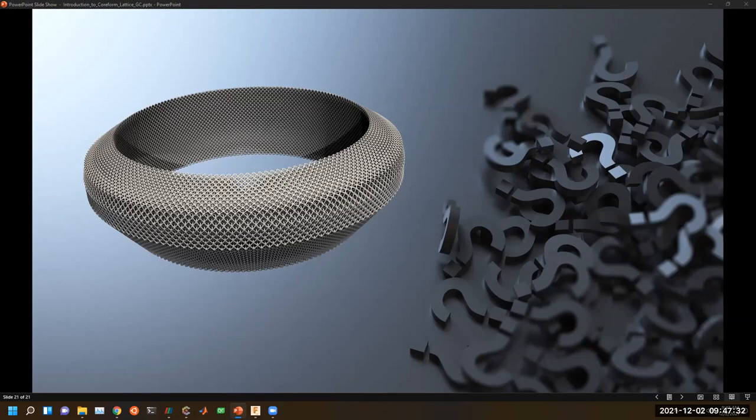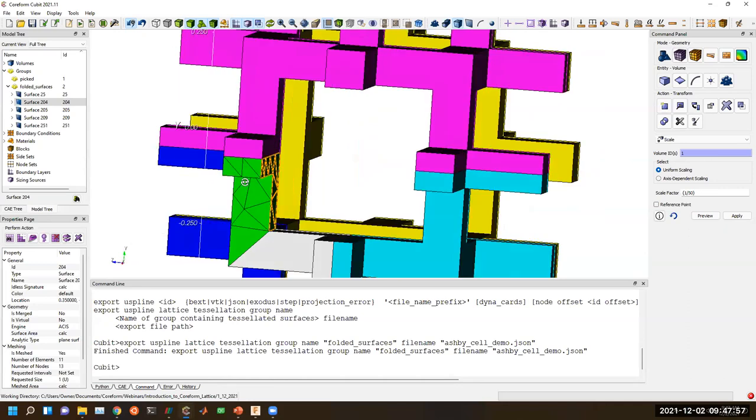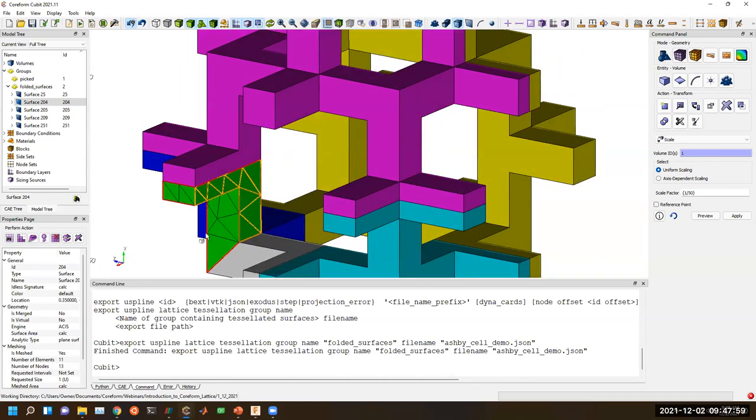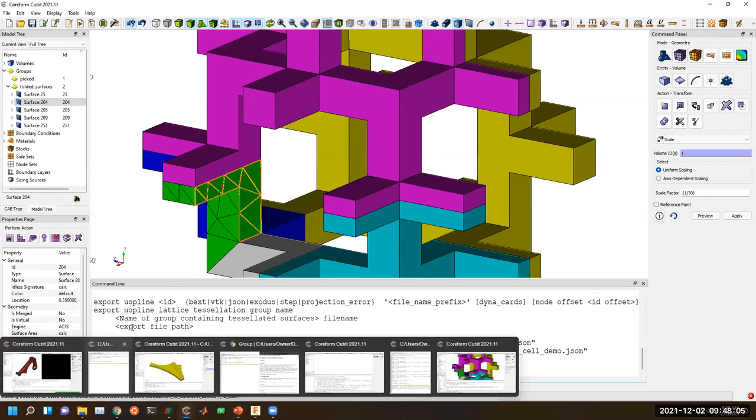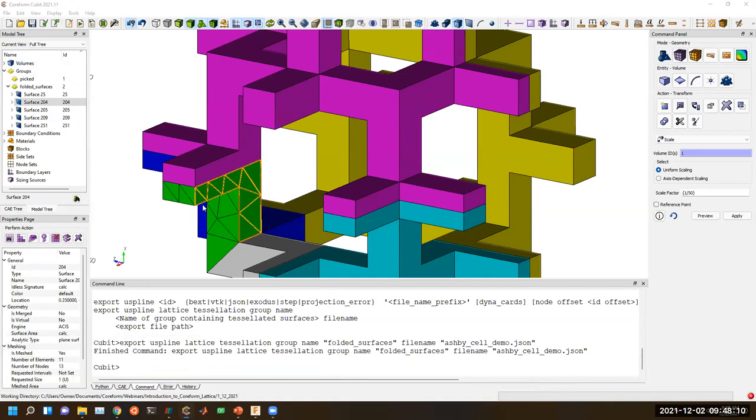We got a question from Ron. Will you be able to use the lattice as a geometry that could then be meshed and exported to an FEA solver like Abaqus? So at least right now, the lattices that we can export are exported as triangle tessellations. And they'll inherit that tessellation from this tessellation you see here. Now, once you have, say, one of these solid, let me see if I can actually import maybe a demonstration here.